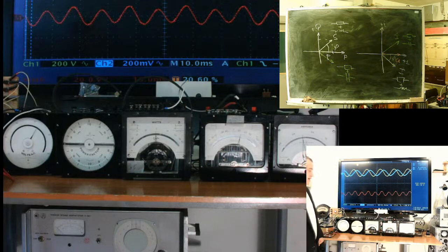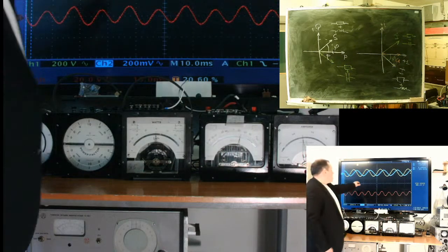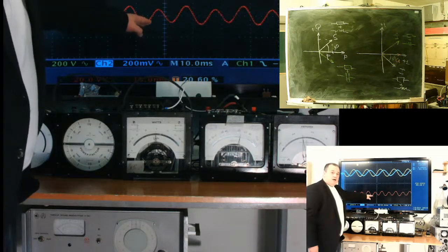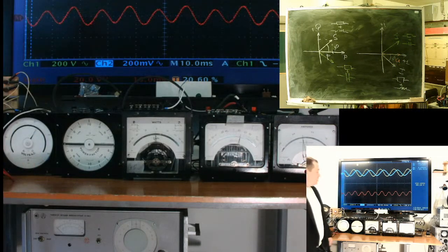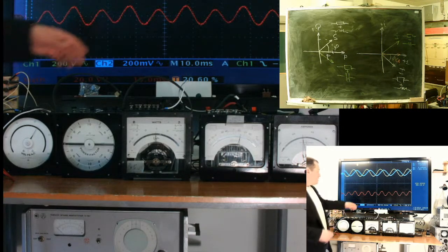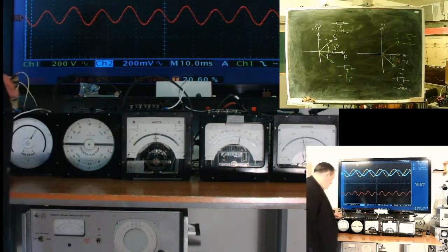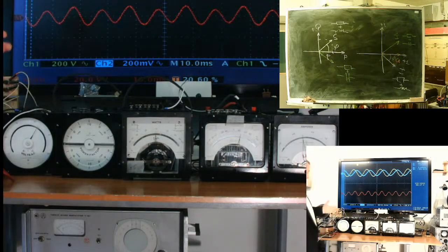15 units of reactive power consumed. Current is lagging relative to the voltage. Ideal coil, ideal inductance. We only take reactive power from the system. So take a look at the red line. It's a kind of oscillation. Energy taken from the net to energize the magnetic system of the ideal coil and then sent back to the network. Real active energy consumption now is 0.